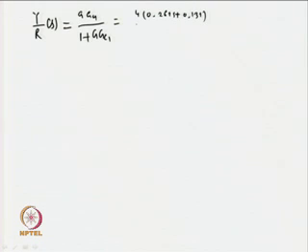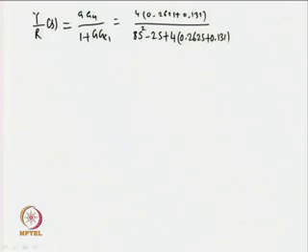closed loop system. When GC2(s) is assumed to be 0, the closed loop transfer function with respect to the reference input can be obtained as Y upon R(s) equals G GC1 upon 1 plus G GC1, since GC2 equals 0, which can again be written as 4 (0.262s plus 0.131) upon 8s squared minus 2s plus 4 times (0.262s plus 0.131) e to the power minus 2s.